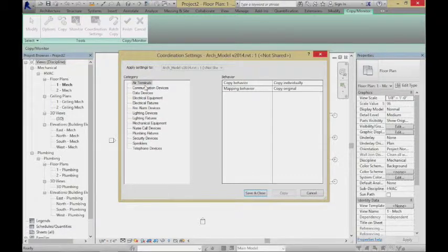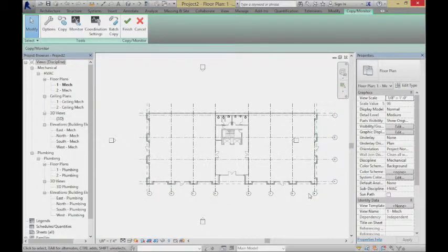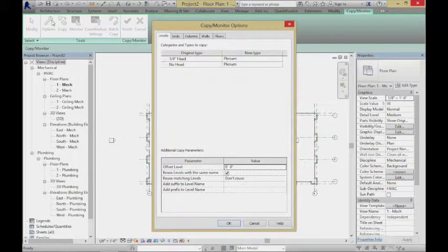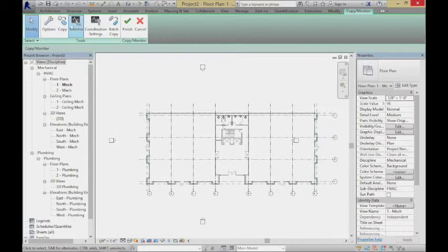Well, we can copy air terminals if you've already put them in, plumbing fixtures, sprinklers. It's a lot of things that you can copy automatically. If the architect's already put some things in the architectural model, you can copy them out. But let me see if we can even define them in here. So levels I can get, grids I can get, columns, walls, and floors are the biggies. I'm going to go after the grids for right now. So how am I going to do this? I can say copy.